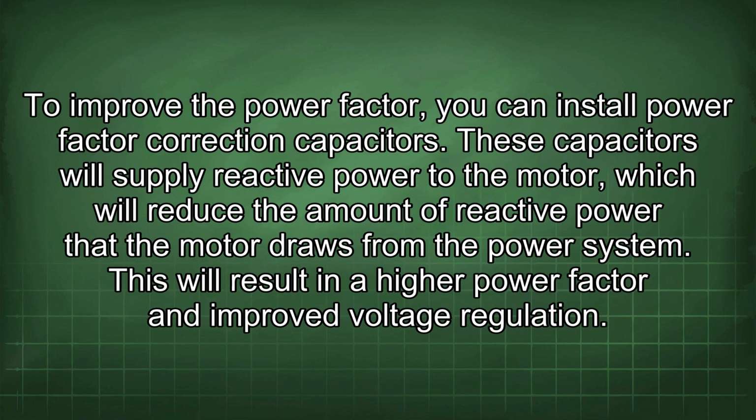To improve the power factor, you can install power factor correction capacitors. These capacitors will supply reactive power to the motor, which will reduce the amount of reactive power that the motor draws from the power system. This will result in a higher power factor and improved voltage regulation.